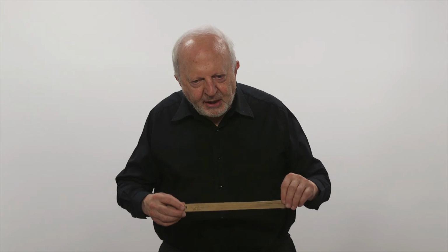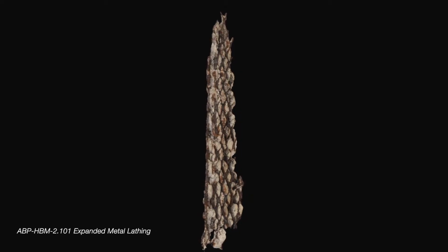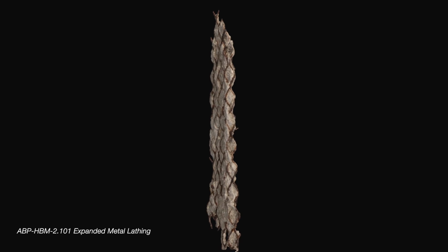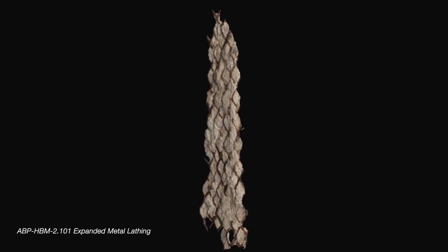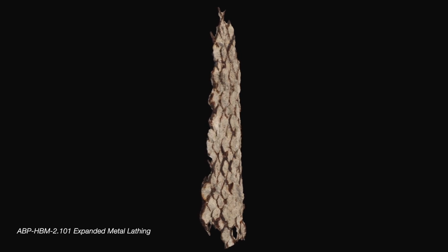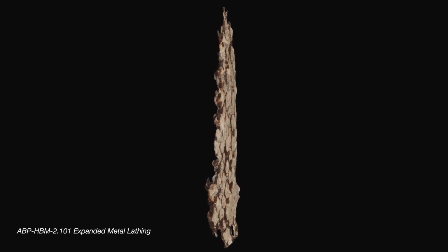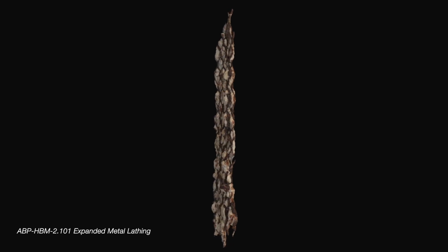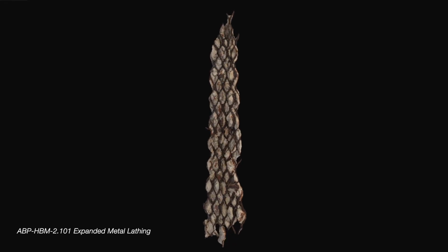However, there were various substitutes, and this is one. This is called expanded metal. Expanded metal achieves the same effect. The plaster can be pushed through it and therefore would bond. Now, it's called expanded because it's made from a single sheet of metal which has a number of little slots punched in it and then pulled out sideways to create a diamond pattern which makes this very useful mesh. The same material came to be used even for some forms of reinforced concrete, although originally it was devised for plastering.